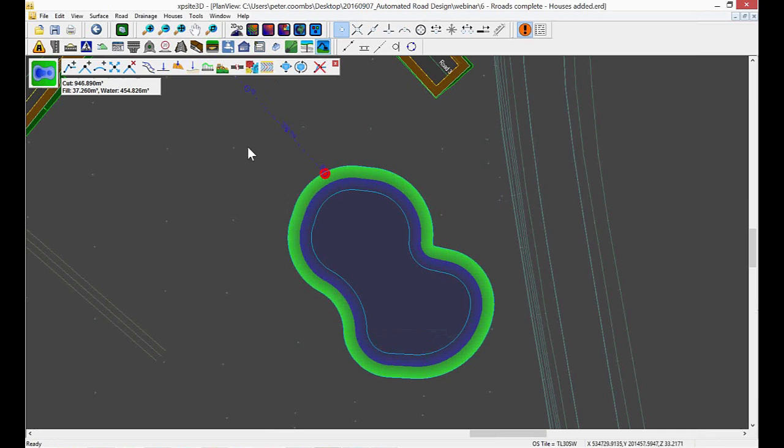Before I export, by the way, I'd need to just notify the program where the outfall point is. So if I go back to my drainage tools, just so the program can orientate itself, which is the upstream, which is the downstream. And I can go to the manhole properties. So if I run along here, you can see that we can create new runs, we can move the manholes around, or add new manholes, delete manholes, delete the pipes or conduits, and we can look at the manhole properties.